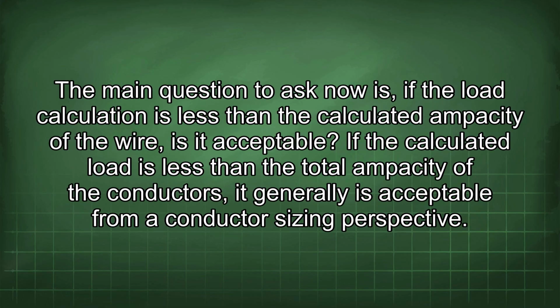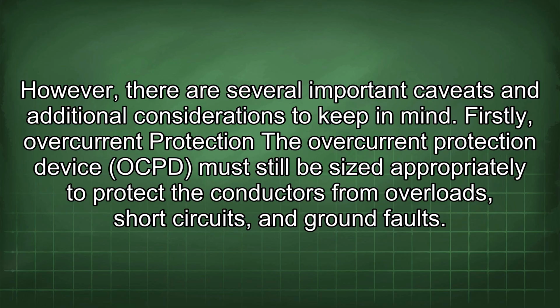NEC. The main question to ask now is, if the load calculation is less than the calculated ampacity of the wire, is it acceptable? If the calculated load is less than the total ampacity of the conductors, it generally is acceptable from a conductor sizing perspective. However, there are several important caveats and additional considerations to keep in mind.